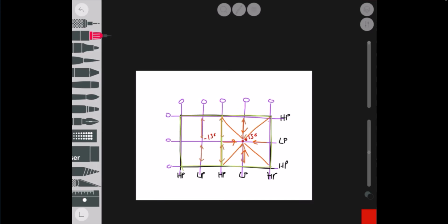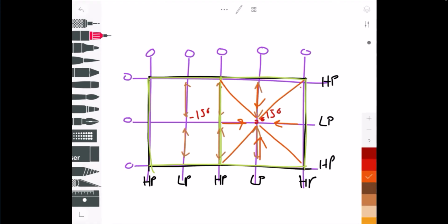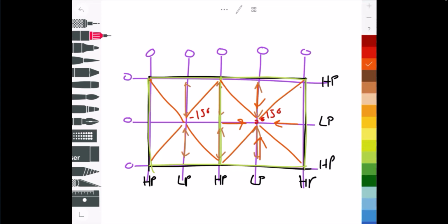Okay, and so if we look at this whole building, again, if we did the same thing, you would end up with a slope that looks kind of like that. And essentially, there's my roof drain. And essentially, you've got no cost to doing that. That's a very straightforward roof plan right there. So obviously rectangles and squares work out pretty well.